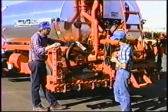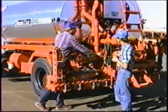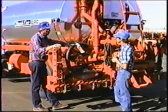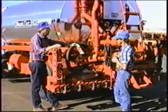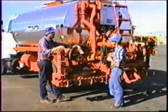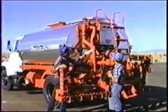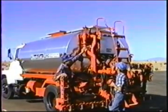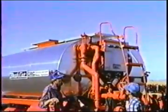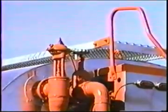positive displacement system, everything has got to go out the spray bar. That is, we've metered the material with the gear pump. If we've metered it with the gear pump, once it's been metered, it's got to go on the ground in order to create that spread rate. If somehow it could leak back into the tank, then we wouldn't be getting that spread rate. First way that that could happen is if we had left the tank circulate line. If that valve were cracked slightly, well, then some of this material that we have metered in order to regulate the spread rate could leak back into the tank. If it's going back in the tank, it's not going on the ground, and our spread rate on the ground